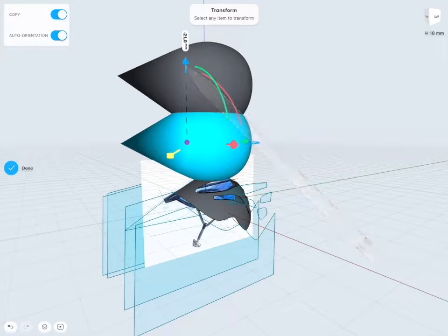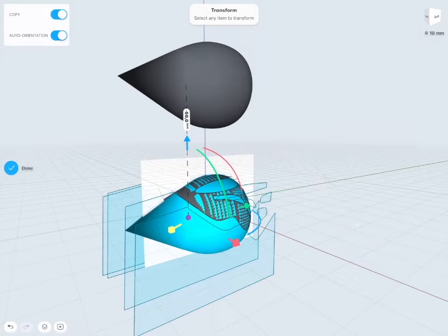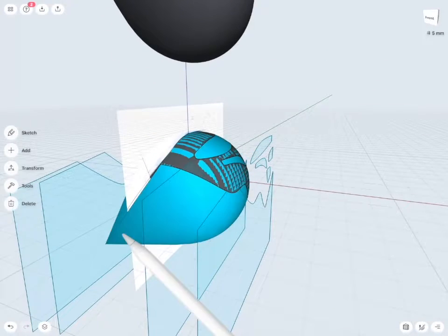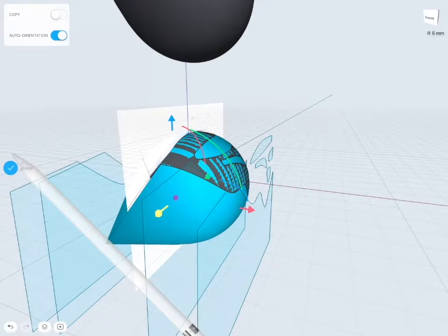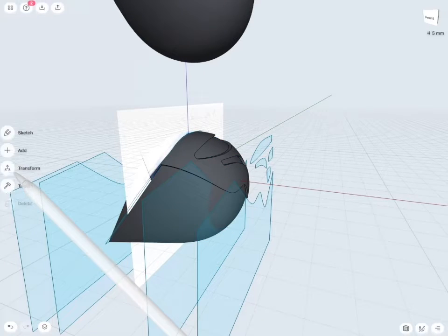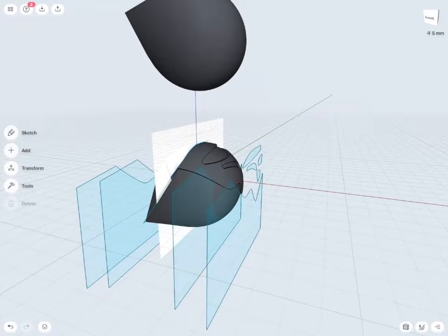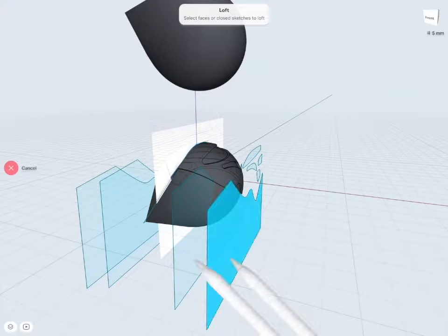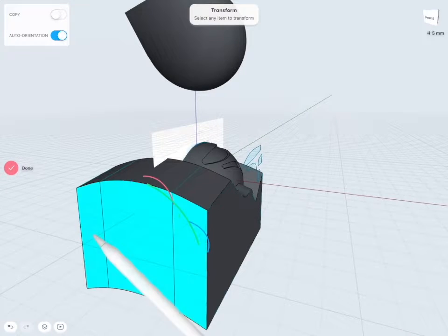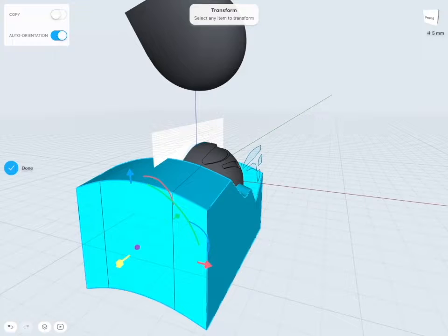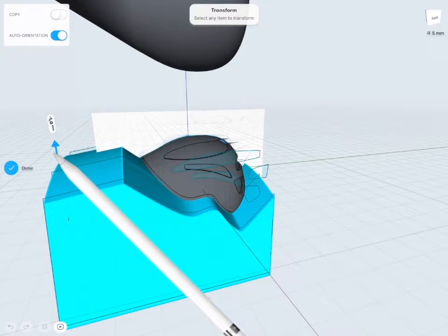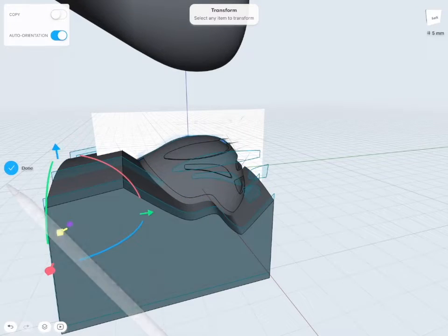We might need to use this revolve shape again later, so I will make another copy of it. Rescale this shape, but make sure to have the pivot point in the center of the object. Use the previously made profiles to loft again. Yet again, I will move the profile, extrude, and subtract the body.